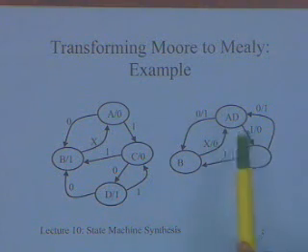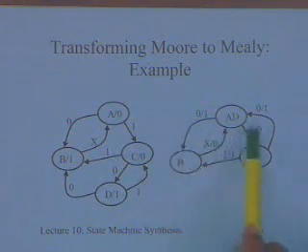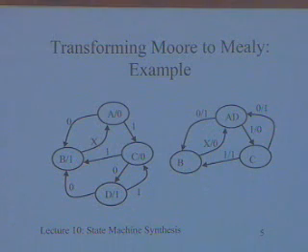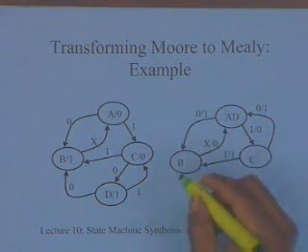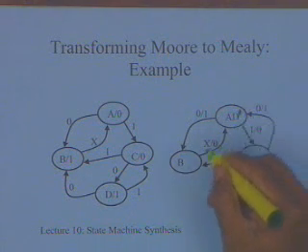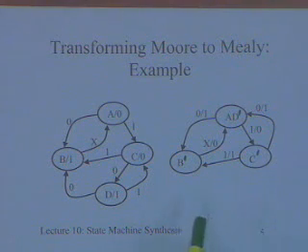So AD is now the same, but now let me see how I am drawing this. I have merged A and D into one state called AD. Previously I was giving different names, I have given the same name here. So let me just differentiate by calling them B dash, C dash, AD dash.